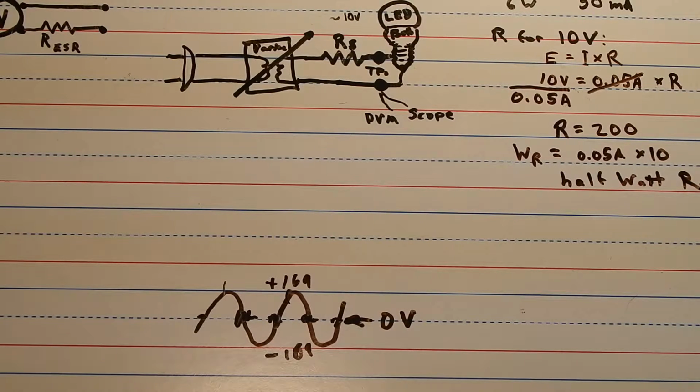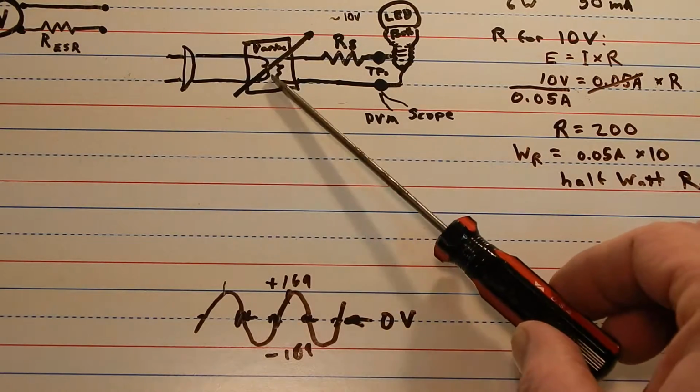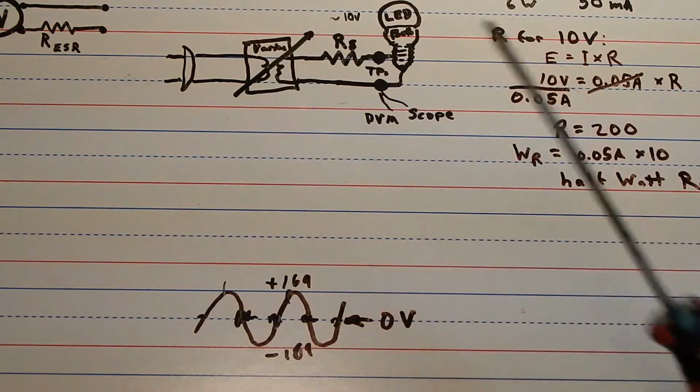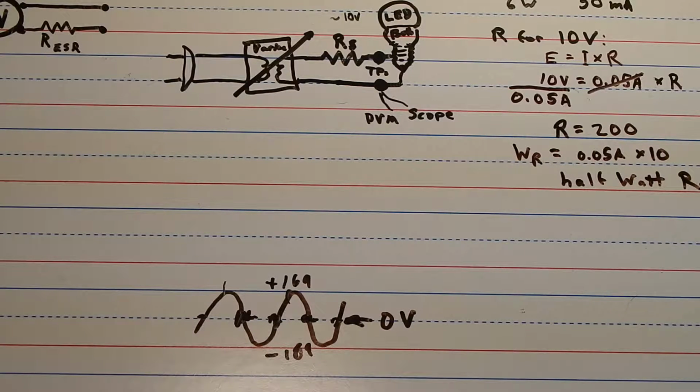But since I have issues with dimmers anyway, the 120 volts isn't that urgent. I needed an isolation transformer. A variac is not necessarily an isolation transformer. Don't assume your variac is going to give you isolation. You have to test that, and in most cases they won't give you isolation.